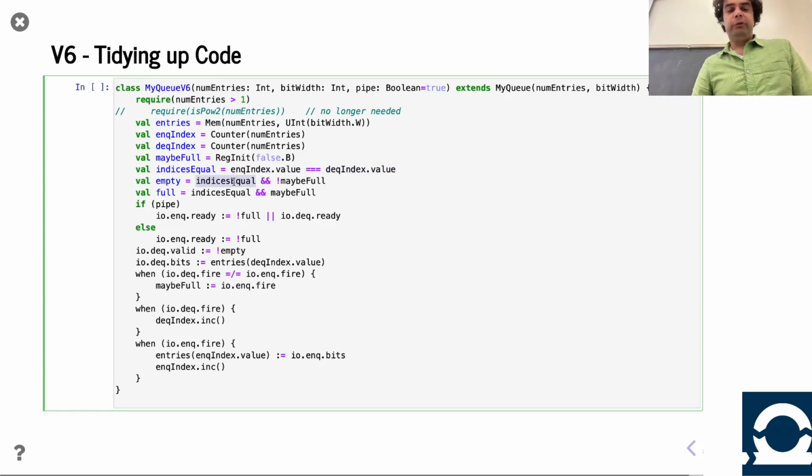This replacement, having this individual signal there instead of having two equals tests here, is not going to have any noticeable change in the hardware. Not because it's small, but because it's called common subexpression elimination. Tools do it just fine. They will figure it out on their own. But as a human, I did common subexpression elimination manually because maybe it makes the intent more clear. We're saying, hey, the key thing is these indices are equal. By labeling this comparison and using that label, someone reading this can perhaps better understand what's going on here.